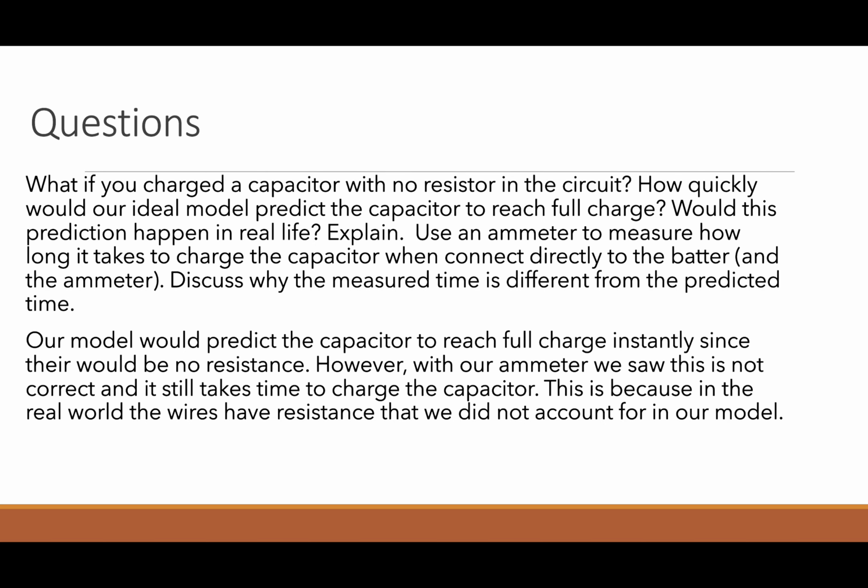Questions? What if you charge the capacitor with no resistor in the circuit? How quickly would our ideal model predict the capacitor to reach full charge? Would this prediction happen in real life? Explain. Use an ammeter to measure how long it takes to charge the capacitor when connected directly to the battery and the ammeter. Discuss why the measurement time is different from the predicted time.